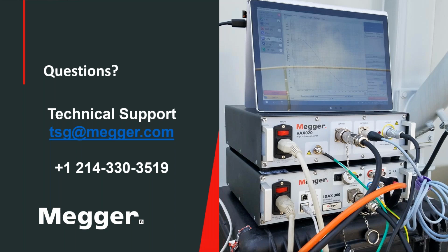All right, so let's jump into your questions. The first one is for Sanket. Where do you use the VAX 220 and the VAX 230 that can do a DFR test for up to 14 kV all the way over to 20 kV? As Diego mentioned, sometimes you might be testing in high noise environments where there's a high amount of EMI, and that can cause noise in your DFR measurements. In those cases where you want to apply a higher voltage to overcome the noise level, you would use the VAX to amplify the voltage and to test at a higher voltage.